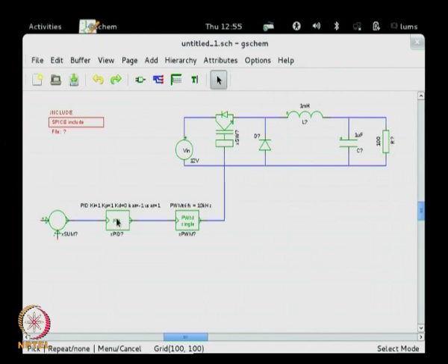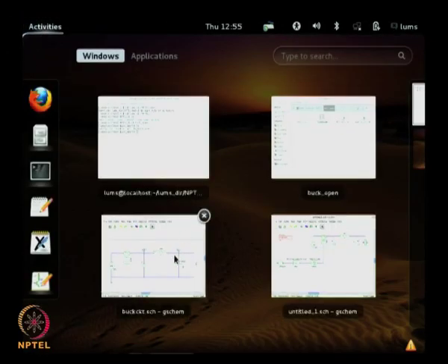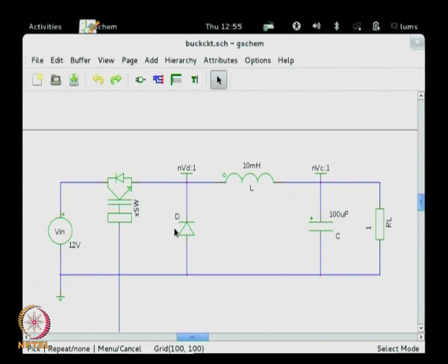Now, all those logic and the equations are in a file called a sub circuit file, a sub file, and you have to point to that, so that the model can be taken from that file. So, just include that file there. After you have included that file, we will have this completed circuit. Do not forget to put the ground. Every circuit should have a ground.